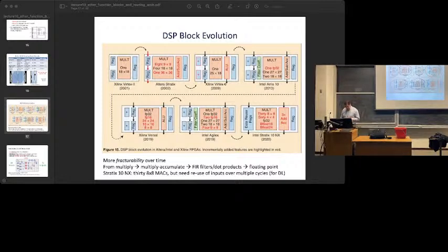So a recent chip from Intel has a lot of multipliers. So 3 8 by 8 multipliers, or you could do 6 4 by 4, which is a lot more than any of these other ones. You can see this one could do, you know, 1 27 by 27, or 2 18 by 18, or 4 9 by 9. So I could split 4 9 by 9 into 8 4 by 4s, but this is a lot more than that. This is like 6 4 by 4s, and, you know, 3 8 by 8. So that's kind of different. So let's look at what that one is.